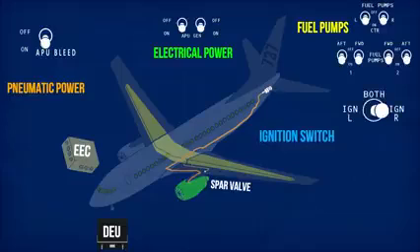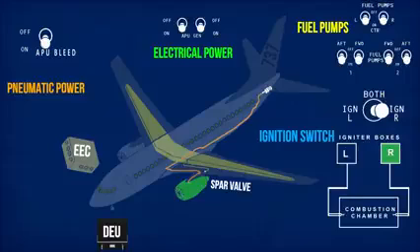Ignition switch position has to be changed. For redundancy, each engine has two ignition systems, left and right. Standard procedure requires changing the switch position before each start.